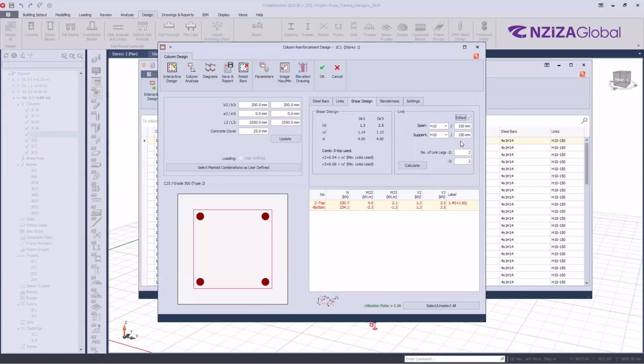However, know that whenever you are changing this, it's up to you. You know what you are doing. So, for example, if the calculated spacing is 150, and I put 200, I'm messing up everything. However, I can reduce this spacing, but I cannot increase it, because as long as you increase the spacing, you are reducing the strength.